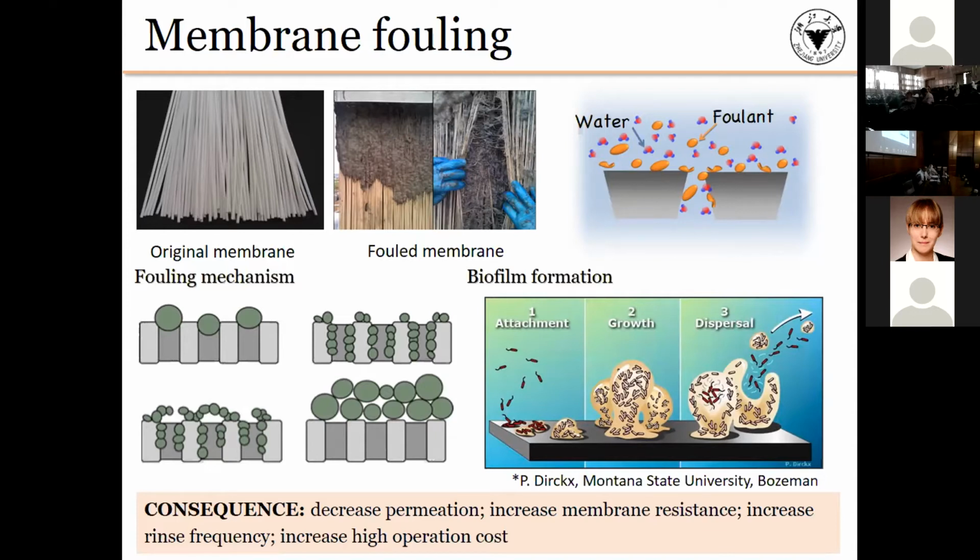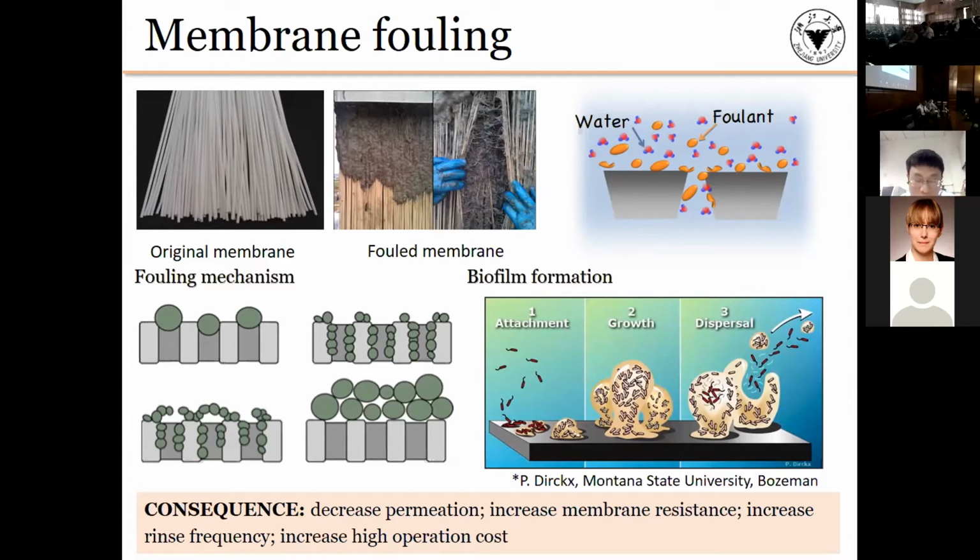Surface property is different from the organic foulant. The bacteria can not only attach on the surface, but also grow on the surface. Moreover, the dead bacteria, as well as the cell matrix, become another type of organic foulant which covers the surface and blocks the pores. So it's important to reduce the foulant adsorption and also avoid bacterial growth to decrease membrane fouling.